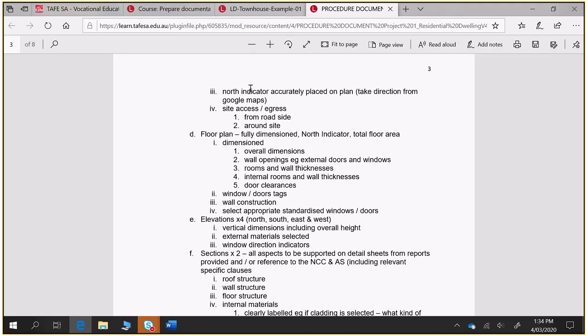I want the north arrow to be the same across all of your drawing sets. All right. So there are several options. One is you can put in a site plan. If that site plan doesn't fit properly with your north arrow facing up and you have to make alterations, you can put a north arrow facing another way and then put a note saying please note north arrow differs from other sheets. Or just put in the degrees. And you want to put that in the box. Don't put in the degrees. Okay, because people don't need to know what those degrees are.